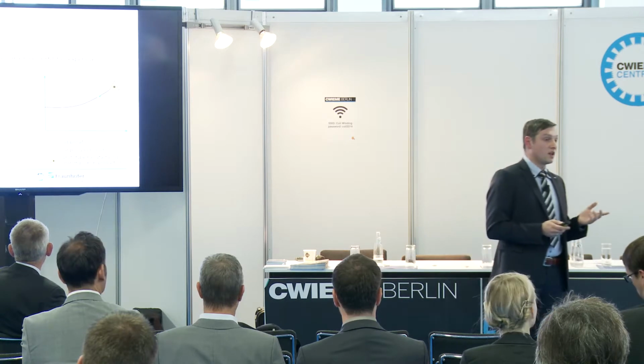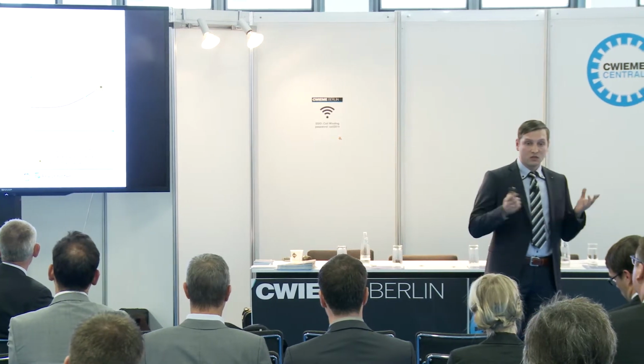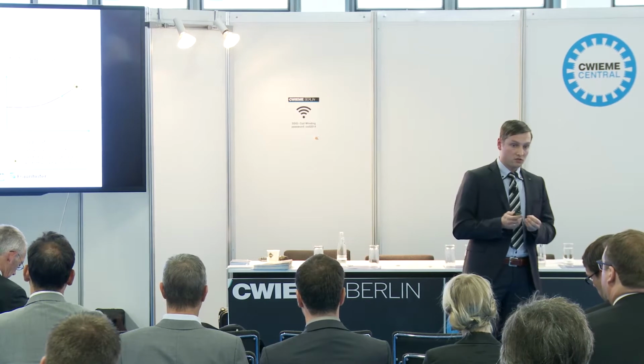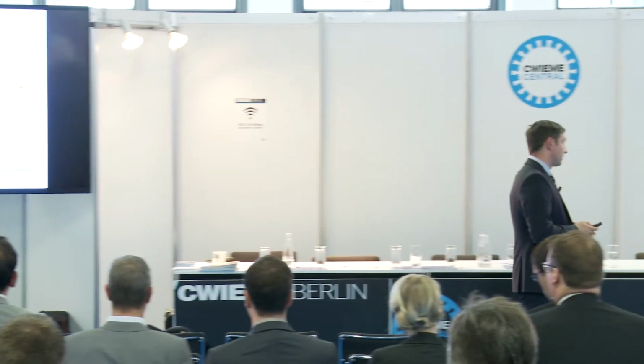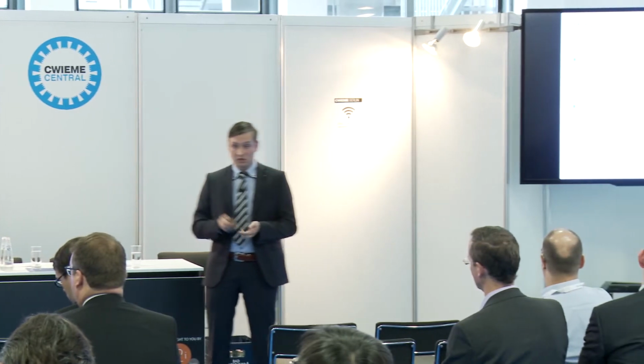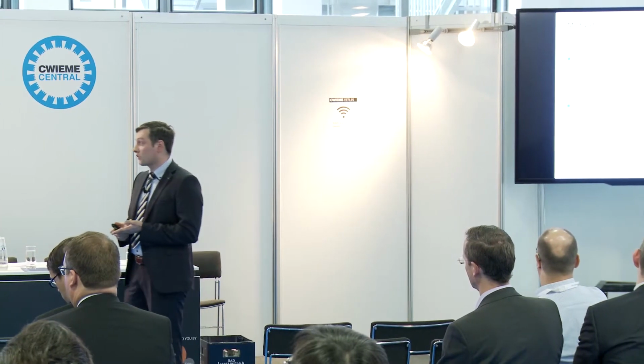I think here we need a manufacturing technique that combines these two advantages. And laser remote cutting is supposed to close this gap between these two techniques because it's wear-free, contact-free, flexible, scalable, and has a break-even point at higher batch sizes.